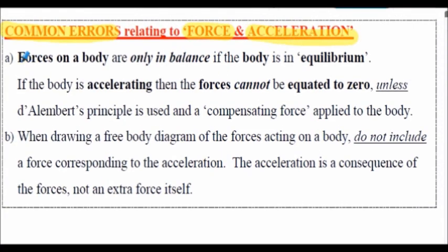So the first point, forces on a body are only in balance if the body is in a state of equilibrium. If the body is accelerating or decelerating, then the forces cannot be equated to zero unless D'Alembert's principle is used and a compensating or inertial force applied to the body. Applying D'Alembert's principle does put the body in a state of equilibrium even though it's being accelerated.